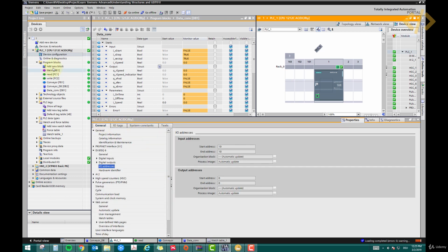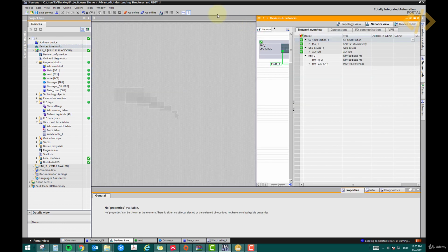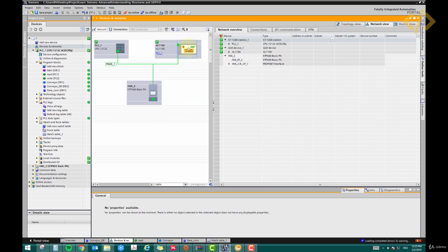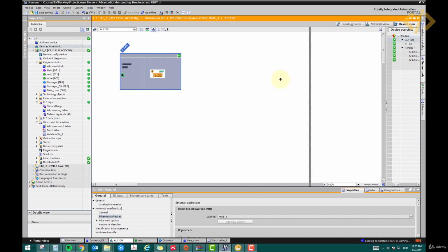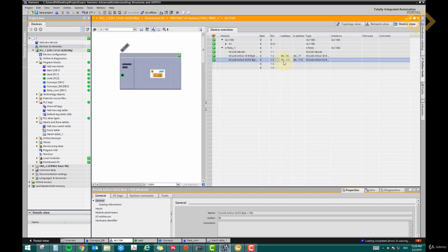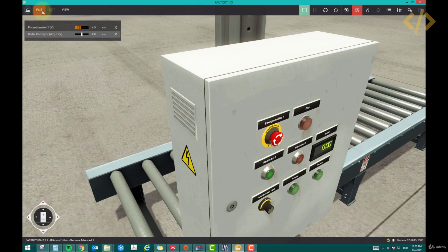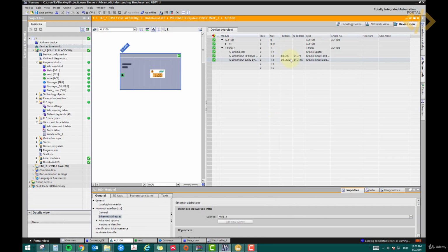All right, let's go to devices and networks, because I remember I have some devices connected here, which is also part of the course. So we have this IO-Link device. I think this will be a conflict. We will learn about that later. If I go inside this device and notice its IO addresses, here is a problem. This is reading from 90 to 122. So this address space has been reserved by this IO-Link, and because my ID 100 falls into this range, there's a conflict.